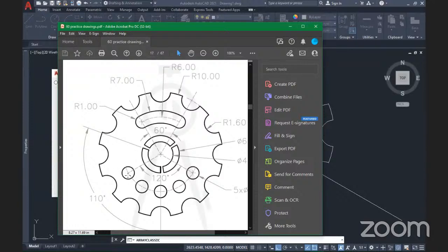If I had started here, I would use a positive 120, which is normal 120. But since I'm coming from my right to my left, I need to use a negative value to tell AutoCAD that, okay, I want this to be reversed. Instead of it going this other way, I want it to be reversed, coming back clockwise. I need it to be clockwise direction. I don't want it to go anti-clockwise, that is the default direction.